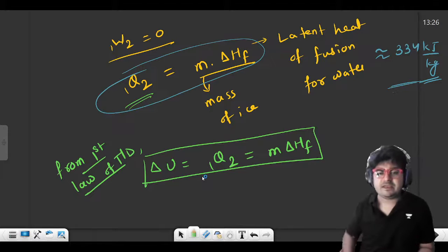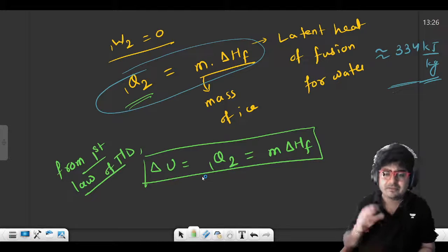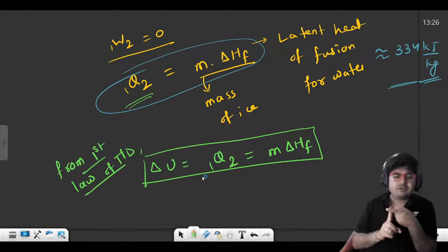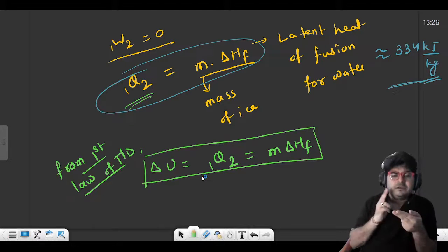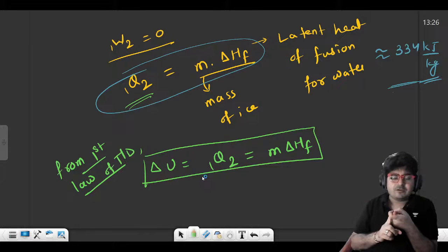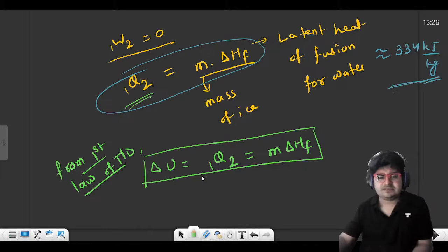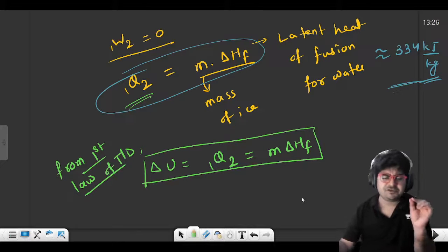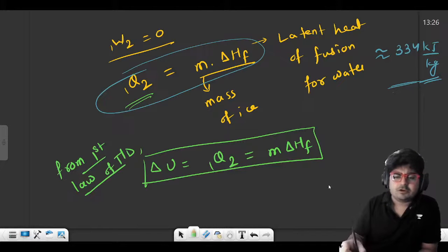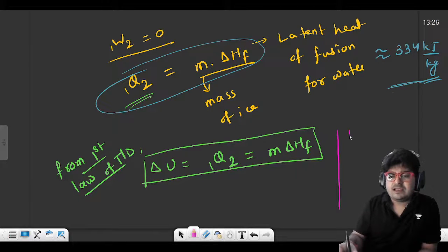This is the thermodynamic explanation, thermodynamic analysis of the process. Melting of ice. First law of thermodynamics we have applied. Internal energy concept we have applied. We have seen the amount of heat required. We have seen the work done here will be zero. This is your thermodynamic consideration basically. And further, if you want to explain, so you can talk about the isothermal and isobaric processes.